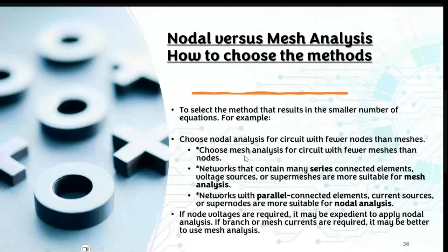Then you can choose mesh analysis when you have fewer meshes than nodes. Also note that networks containing many series-connected elements, voltage sources, or super meshes are more suitable for mesh analysis. If you look at series-connected elements, where you have the voltage source and the current source in series, you might want to opt for mesh analysis.